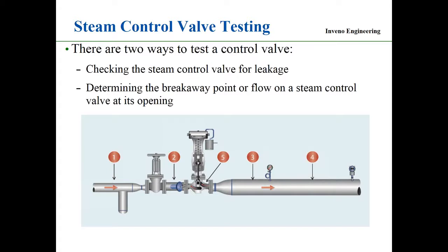Oh, I think I recommend not using orifice steam traps. Then you don't have to worry about testing them. You can't test an orifice steam trap. They're always blowing through. So, note to that person.